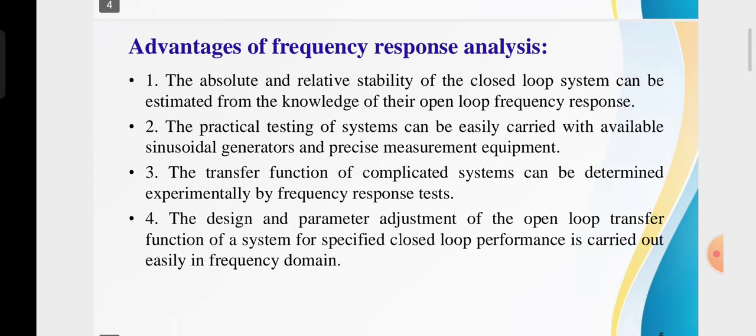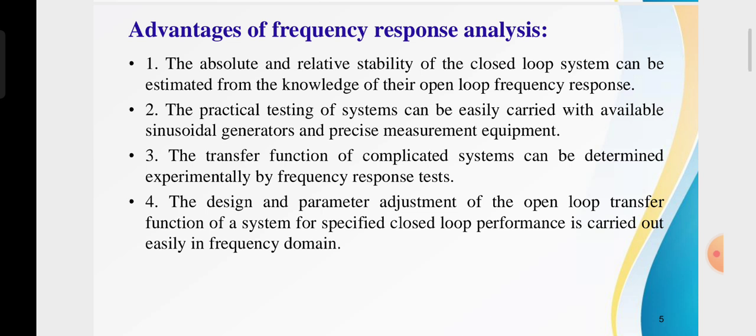And what are the advantages of frequency response analysis? The first point, the absolute and relative stability of the closed loop system can be estimated from the knowledge of their open loop frequency response. And second, the practical testing of systems can be easily carried out with available sinusoidal generators and precise measurement equipment. Third, the transfer function of complicated systems can be determined experimentally by frequency response tests.